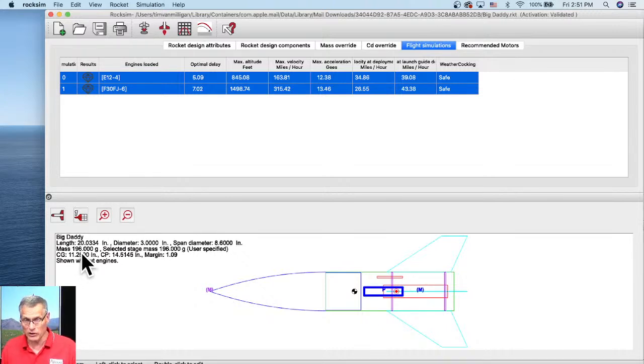The most accurate is the exact weight of the rocket as you built it. So we talked about this last week, is how do you know your RockSim file is correct? And you have to actually compare it to what's in real life. So until you actually build it, everything is hypothetical. So like in that Katana rocket that we just did, everything was hypothetical until we actually compare it to what's in real life. And then from that point, you have to adjust your RockSim file to match real life.